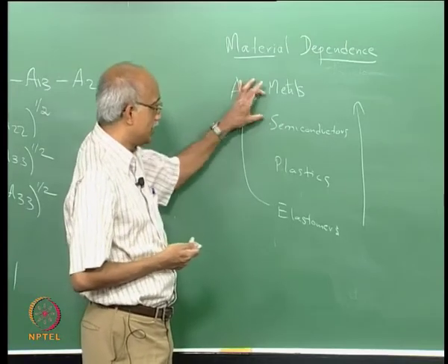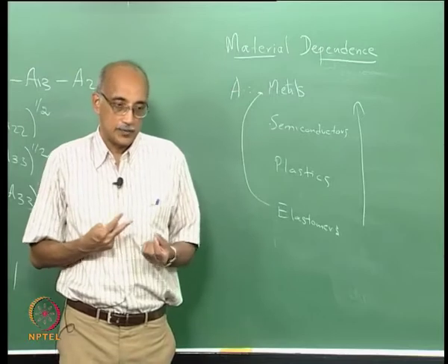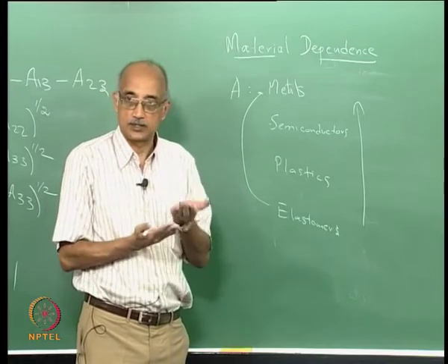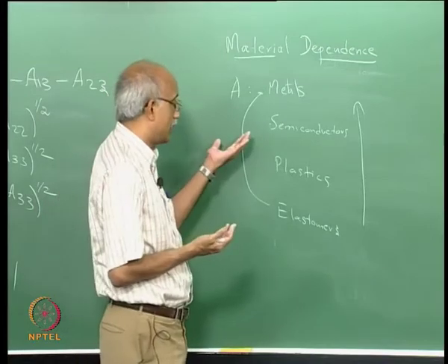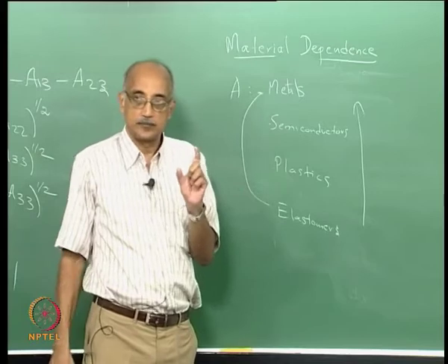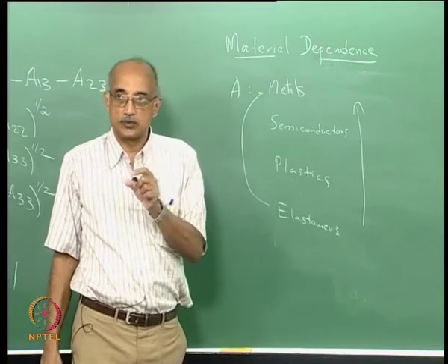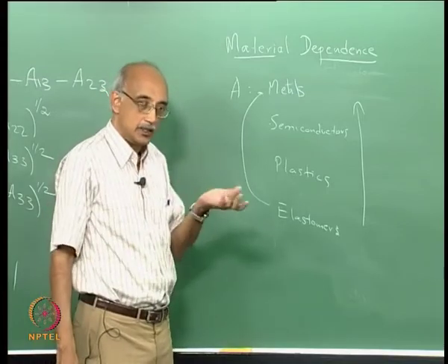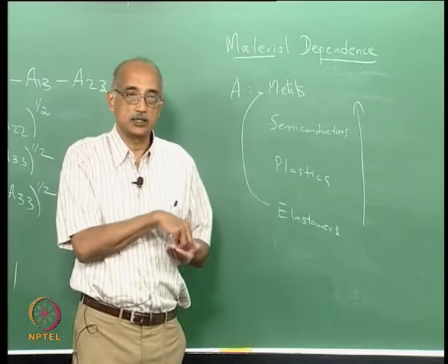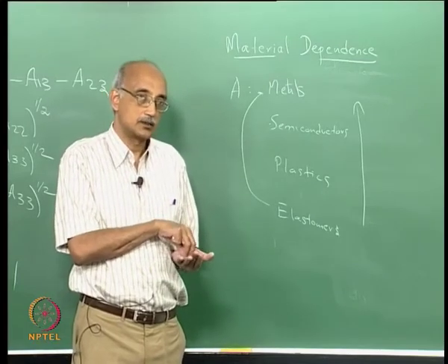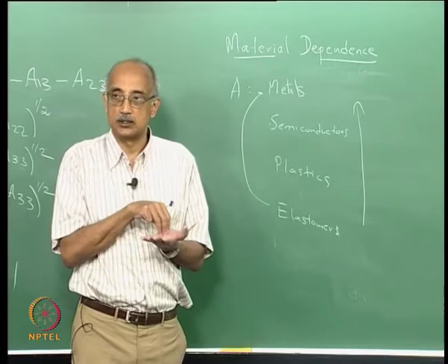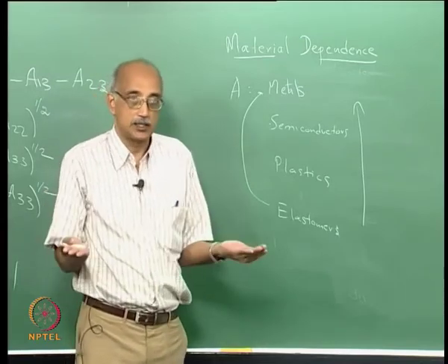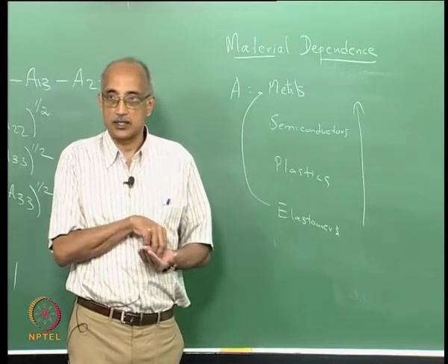Also, you know, the combinations are interesting. When you have, for example, a silicon oxide particle approaching, let us say, a silicon surface, the Hamaker constant for silicon is greater than the Hamaker constant for silicon oxide. So, what does that imply? The affinity of silicon for the silicon oxide that is approaching is greater than the affinity of the silicon oxide for the silicon. Now, again, that is mostly positive, because that means that if you are trying to make silicon, silicon oxide is not going to act as a contaminant.